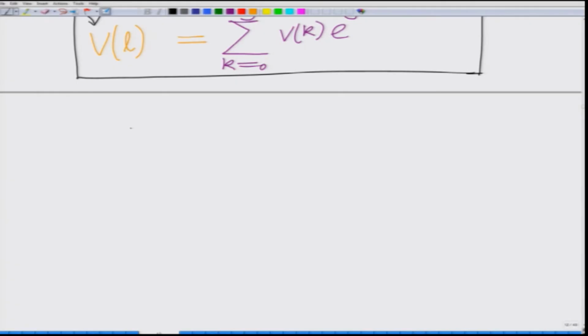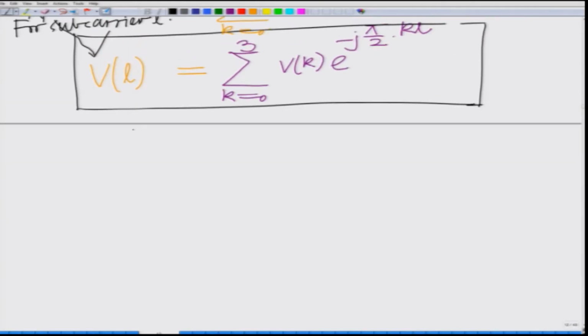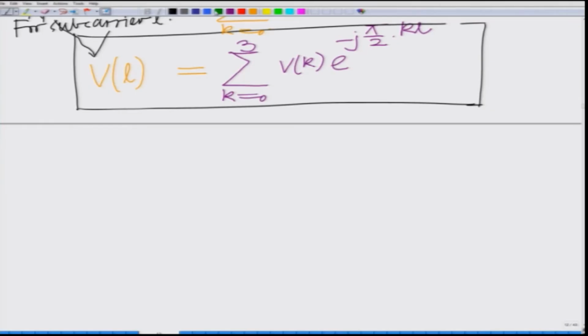And therefore, now you have the frequency domain. Remember, in the frequency domain, we have the FFT of the output y is equal to the FFT of the channel h times the FFT of the samples x, which are the symbols loaded onto the subcarriers, plus the FFT of the noise sample across each subcarrier. Rewriting it, I have FFT of y equals FFT of the channel filter h product.